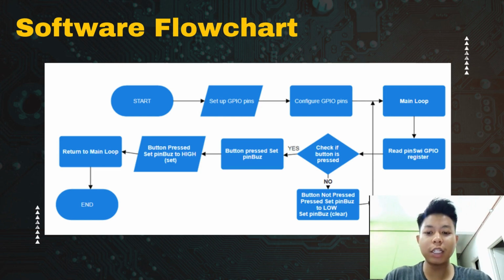In visualizing the functionality of our doorbell system with buzzer, we have condensed the intricate operations into a clear and intuitive flowchart. The journey begins with system initializing, encompassing the setup of the Intel Galileo Gen 2 board, component connection, and GPIO pin configurations. The heart of our program lies in the main loop, where we continuously monitor the state of the doorbell button.